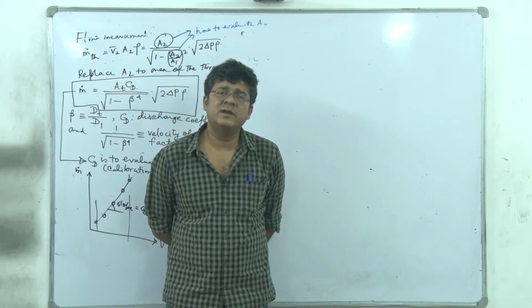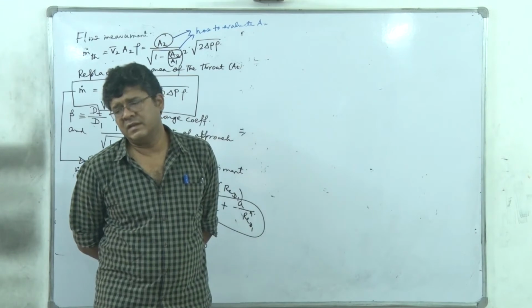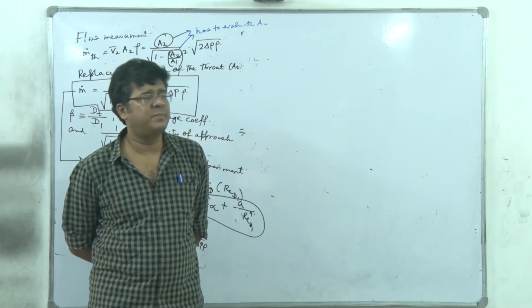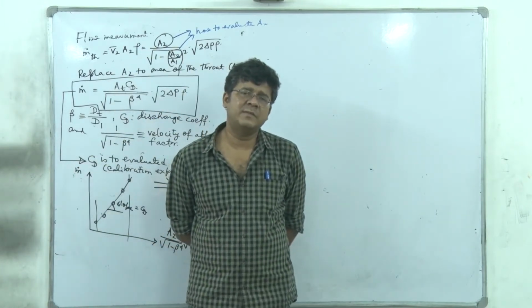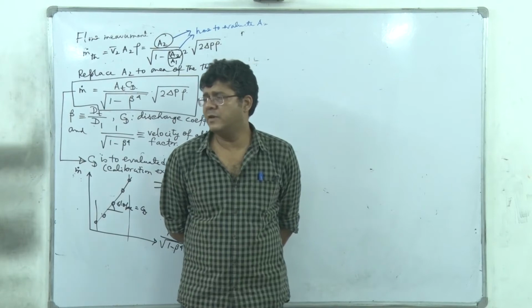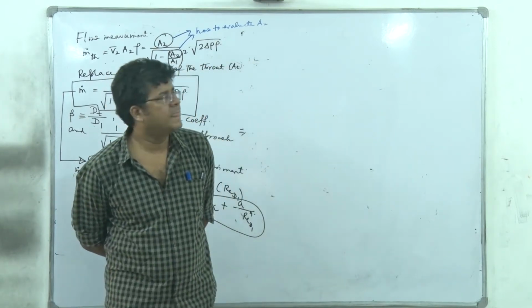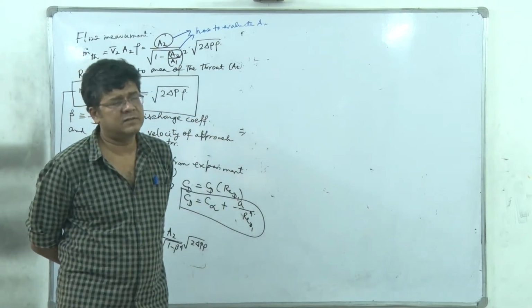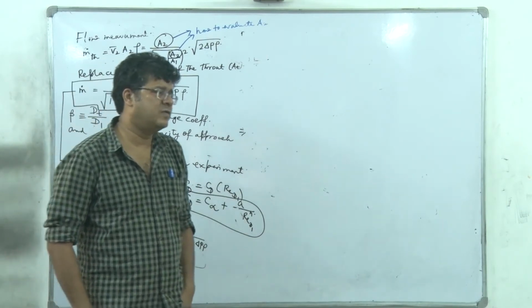Whereas in Venturi meter we have an excellent pressure recovery. That means that P3 will be nearly 98 to 99% of P1. P3 is the far downstream pressure, whereas P1 is the upstream pressure. So P3 is basically close to 99% of P1, and as a consequence we have a very low operating cost, right? So what meter do we have to choose?